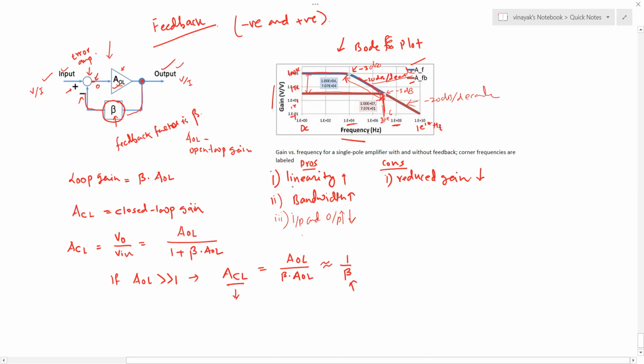And then if you improve the linearity, I forgot to mention, you also improve the distortion problem in the circuit. Your circuit will not produce much distortion. However, the gain will be reduced. We have seen that in the case of transistor circuit. Now, what if the feedback is not properly maintained or achieved?